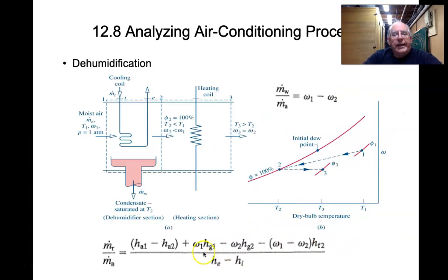And so we come back here, we see the air component, we see in this case here, we see what's happening to the vapor that's in the airstream, and then we see this term right here times the m dot a is the water removal rate times its value of enthalpy. And so this would be the solution to how much refrigerant flow rate do you need to actually perform this dehumidification.